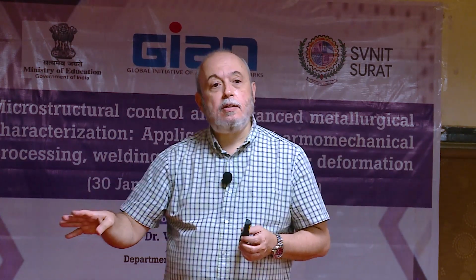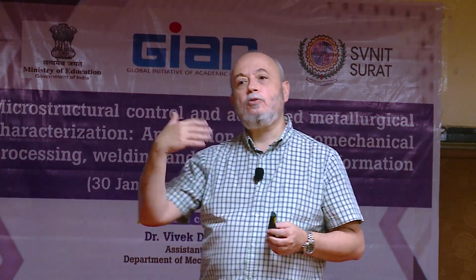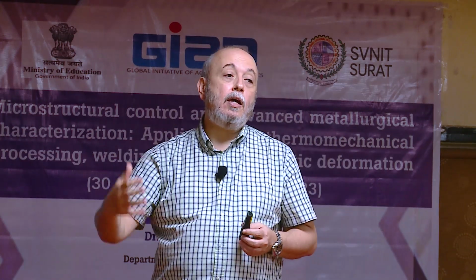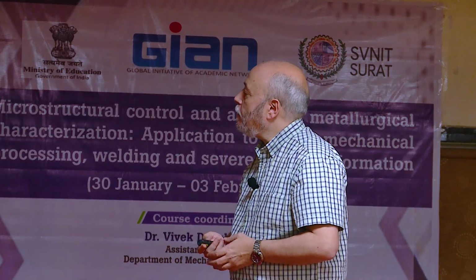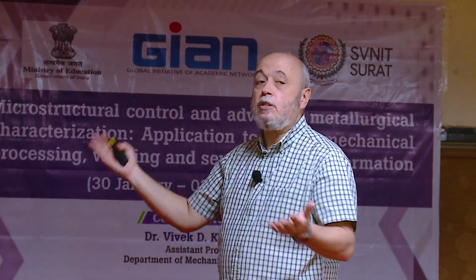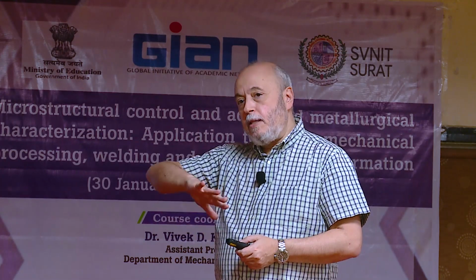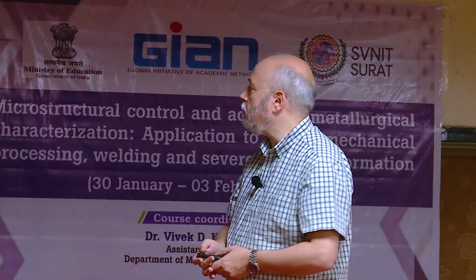And this is important, and this is controlled by the process, especially rolling processes or annealing processes are controlling the texture that you get. This is important, for instance, in electrical steels to enhance the magnetic performance the electrical steels can provide. Or even for carbon steels, the ones we use in the automotive sector, because depending on the texture, you can get more formability in your material. Okay, so this is important.